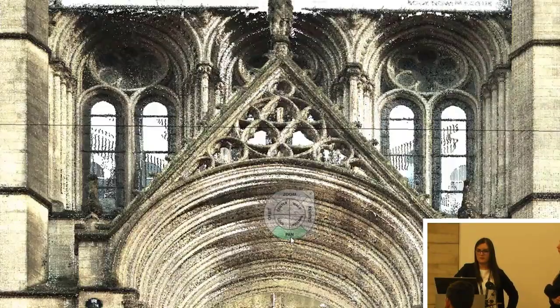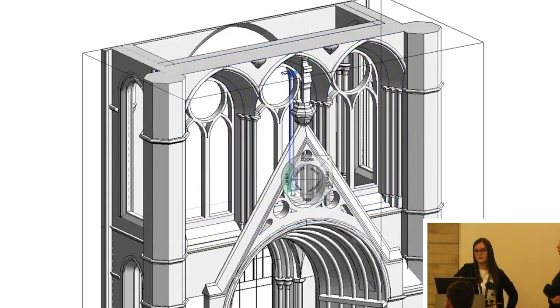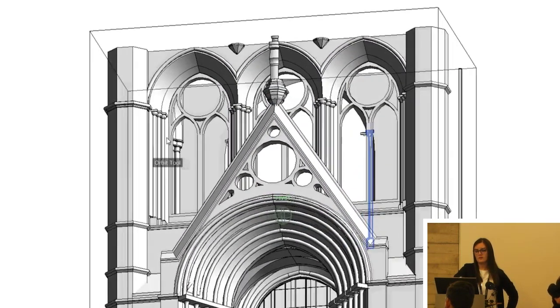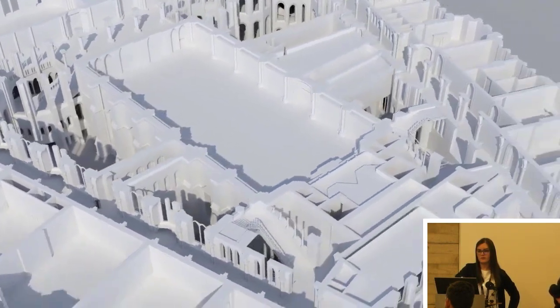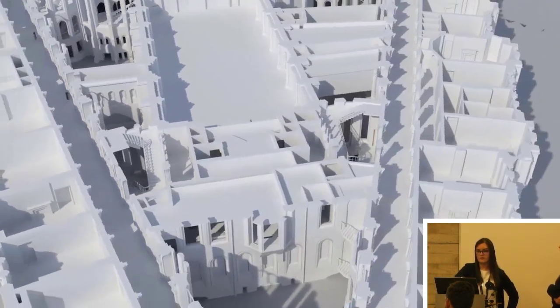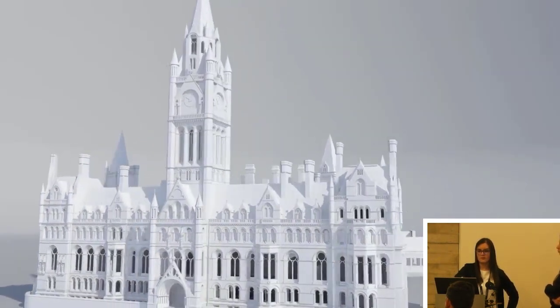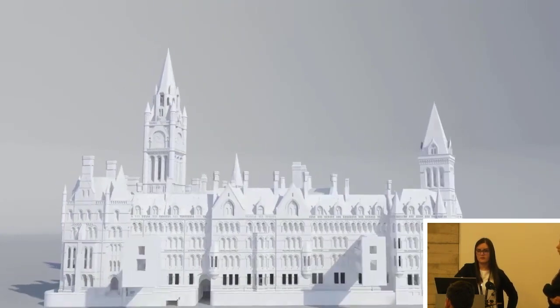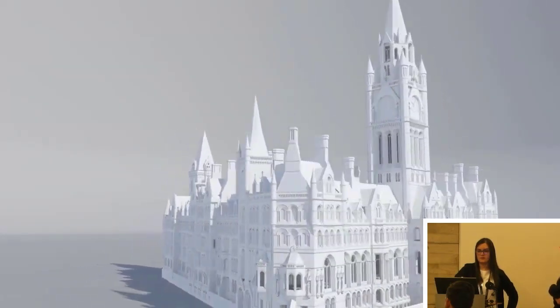As part of our handover of the project, we spent probably upwards of 3 to 4 weeks traversing the whole building with our point cloud and our Revit model, ensuring that each room and the information within that room, structurally and architecturally, had been appropriately captured, to validate the as-built model and give surety and confidence to the technical consultants who were progressing that the data we provided was accurate.